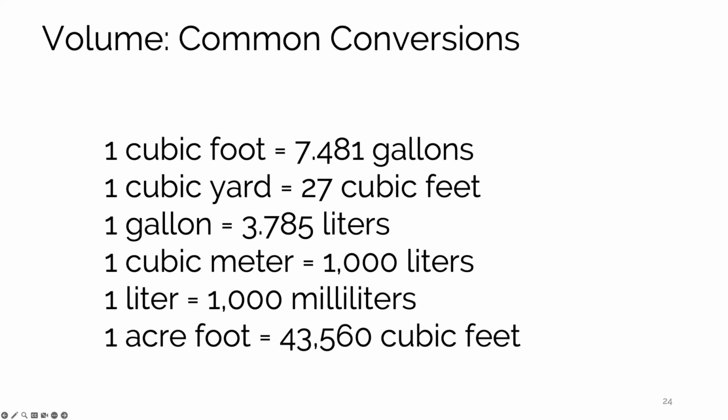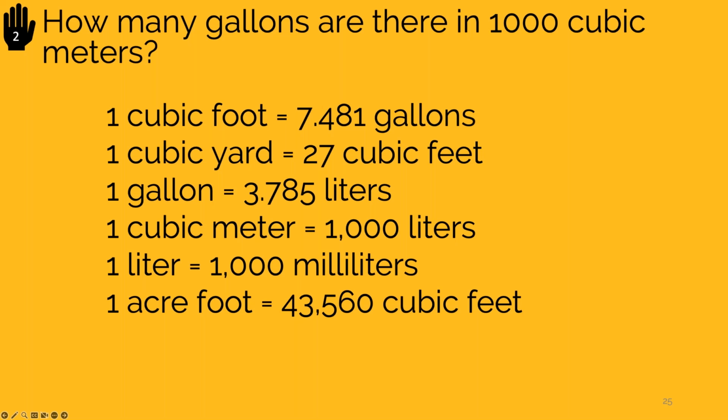And if you're doing practice tests, you'll see which ones show up most frequently, but being able to at least move between cubic feet and gallons and liters, and remembering that a cubic meter is 1,000 liters, not 100 or 10,000, is going to go a long way to helping you do the correct conversions you need to solve these problems, because invariably they give you mixed units to confuse you. So I'm going to leave those conversion factors up.